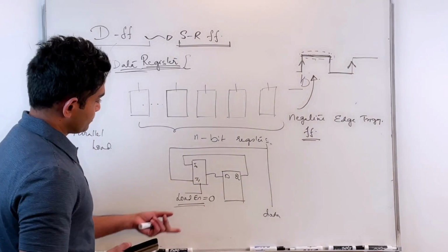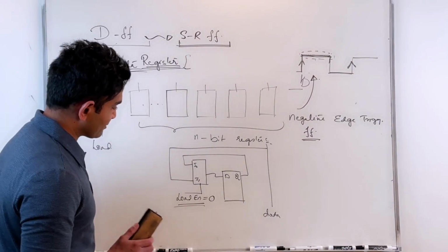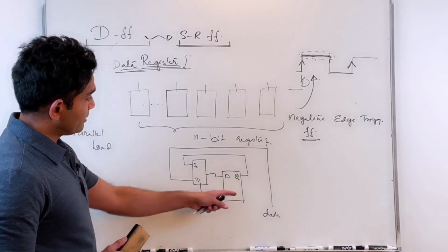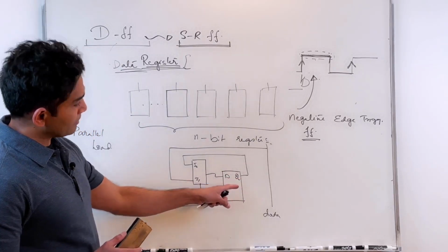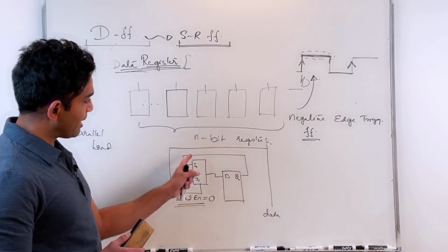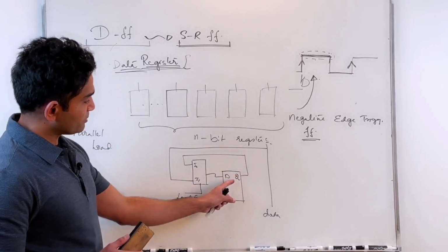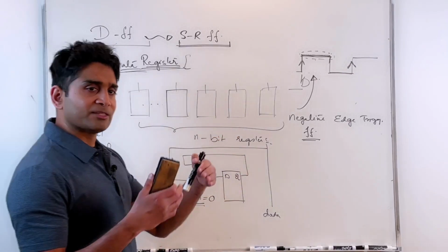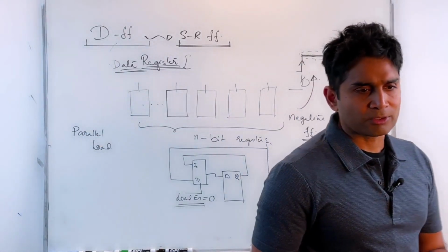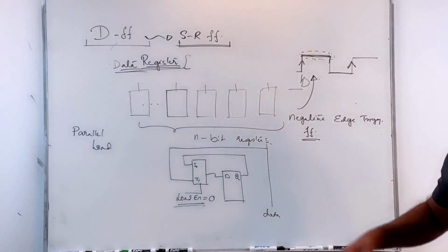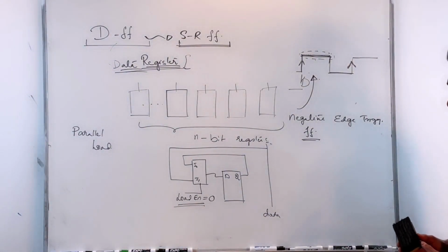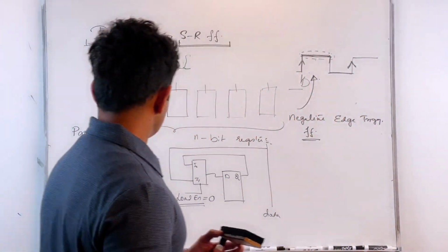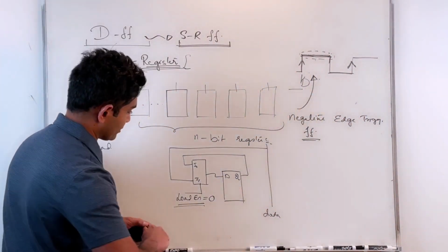All right. So this is what we discussed in the last class. If we put load enable as 0 here, then I'm basically keeping the data in memory because I'm feeding my Q back to D, and then on the next triggering instance, Q follows D, so basically nothing is changing on my Q. So that's the idea behind the setup. This is the load enable.